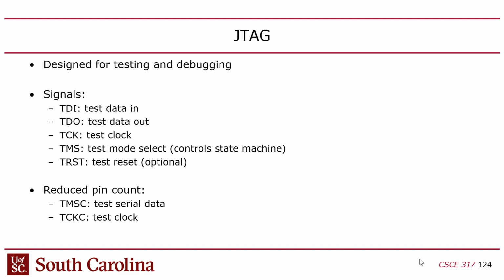There's an array of pins on the back, and you have solder paste on those pads, and then typically a robot would take the chip and align it with the board and lower it down on top of the pads, and then you put it in an oven and cook it, and that melts the solder paste and creates the connection. The balls are actually solder balls.